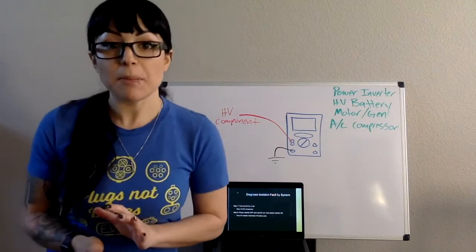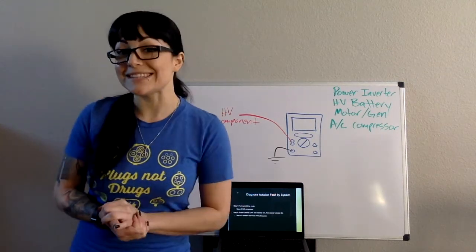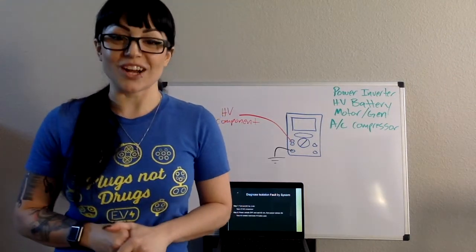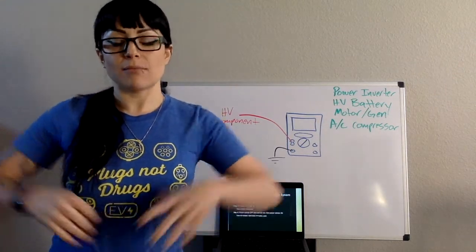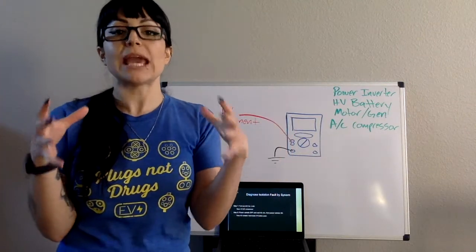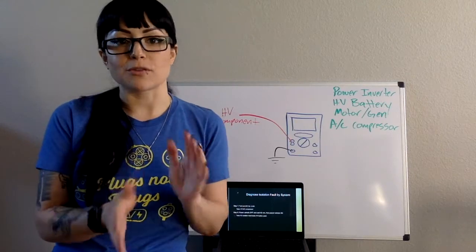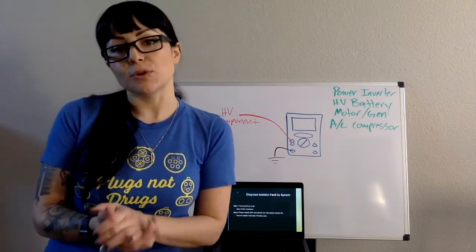And when I say battery pack, if your high voltage controller is inside of the battery pack, it could also be a high voltage controller. So at that point in time, at least we've narrowed it down to the area of the battery pack, and now we can figure out whether it's going to be a battery pack or a high voltage controller.